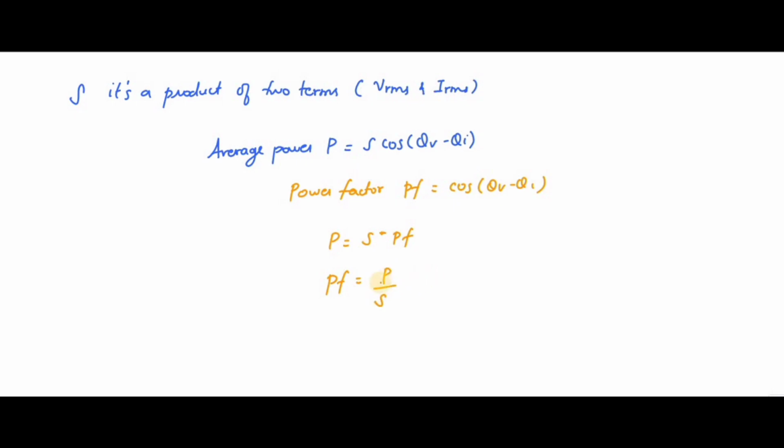So this is also your power, this is also your power. So this is a dimensionless quantity. This is measured in watts, and this is measured in volt ampere. So the power factor is defined as a ratio of the average power to the apparent power.